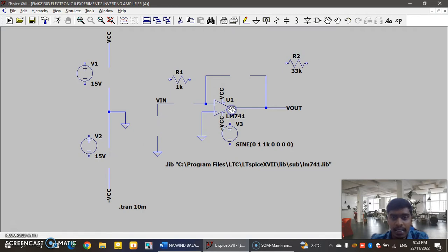So this is the operational amplifier to get the output value, and this one is the inverting, and this one is non-inverting, but the circuit I'm doing now is inverting, so the supply should be on the top, and it should be at the negative terminal. Then this one is the R1 resistor, and my RF resistor I just put as R2, and then I have the power supply.